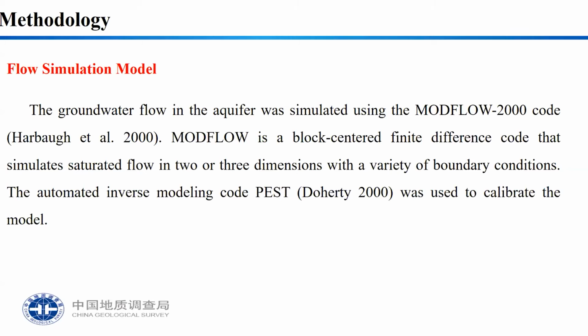In this work, we use MODFLOW to simulate the groundwater flow. MODFLOW is a block-centered finite difference code that simulates saturated flow in two or three dimensions with varieties of boundary conditions. The automated inverse model code is PEST.